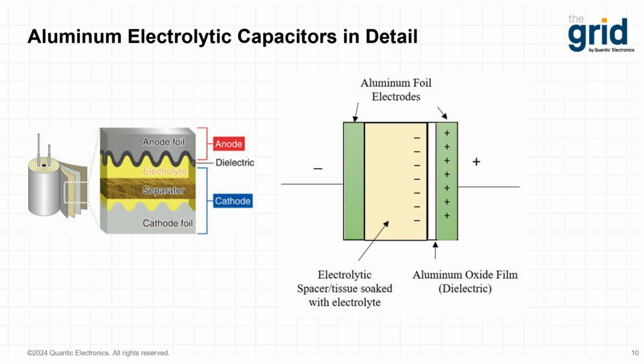Aluminum electrolytic capacitors have an anode that consists of a pure aluminum foil with an etched surface. The etched surface increases the surface area, thus providing more capacitance. During processing, this etched surface aluminum foil forms a thin layer of aluminum oxide. Now, this aluminum oxide is what serves as the dielectric of the capacitor.